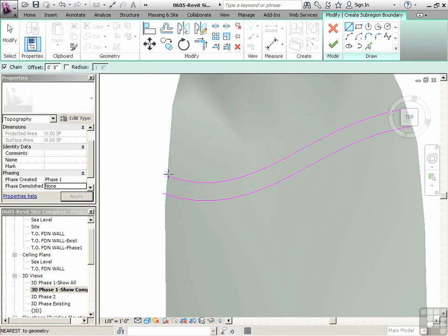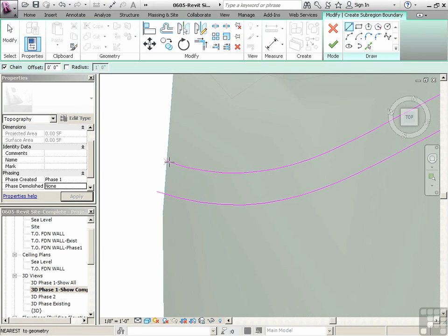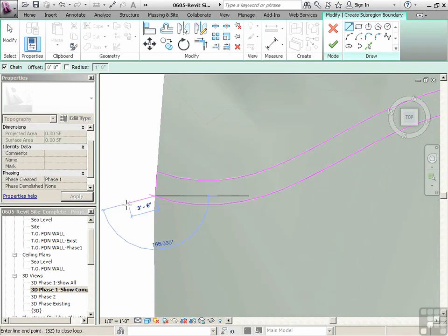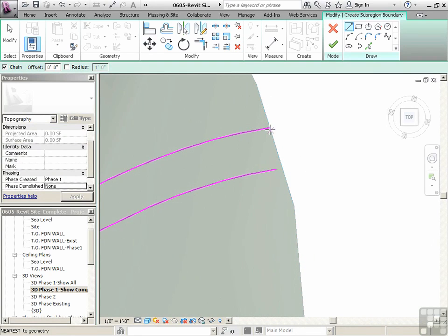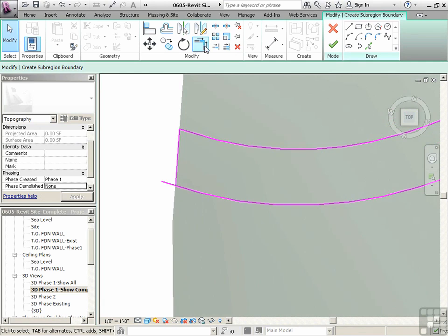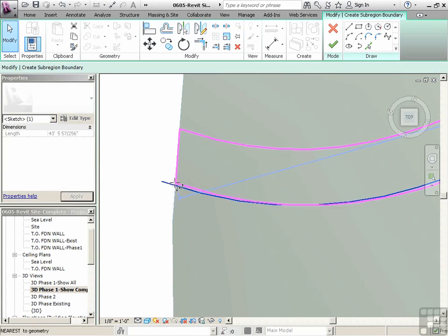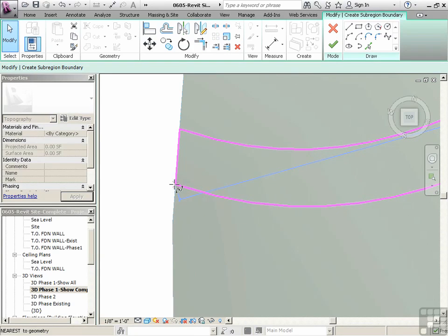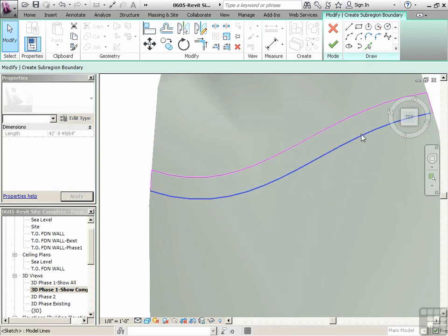We have to close these off. So we're going to draw from snap endpoint. So I'm going to type in SE, and let's just see if it will find it using nearest. Okay, let's do this again. We're going to draw one there, SE. We'll draw this across. Now I'm going to go to fillet, and we're just going to go there and there. Why didn't that work? Let me try this side. Fillet. Nope, splines don't fillet. That's why. Okay, so we can just pull that back using grips, SE for snap endpoint.